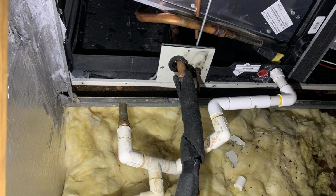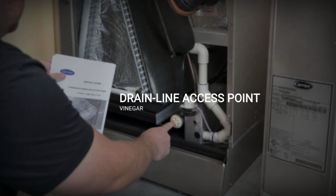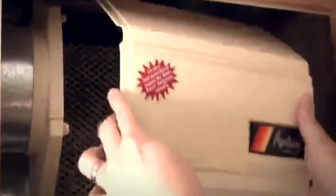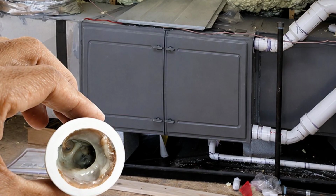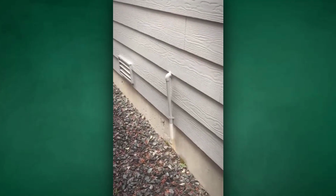An air conditioning system can contain condensate on the evaporator coil, in the drain pan, through a trap, and along the drain line. Each component keeps its own maintenance procedure. Carrier's support for distilled vinegar is tied to the drain line access point. That sentence does not authorize pouring it across the evaporator coil, spraying it into the return duct, filling the drain pan, treating a humidifier, or introducing it through any opening that happens to be nearby. Location changes the materials the liquid contacts. It also changes what can be damaged, what can be flushed away, and whether the homeowner can observe the result.